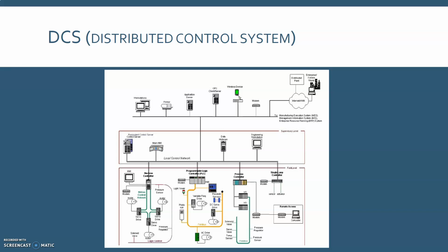Additionally, a field bus allows greater functionality beyond control, including field device diagnostics, and can accomplish control algorithms within the field bus, thereby avoiding signal routing back to the PLC for every control operation. Standard industry communication protocols designed by industry groups such as Modbus and Fieldbus are often used on control networks and Fieldbus networks.